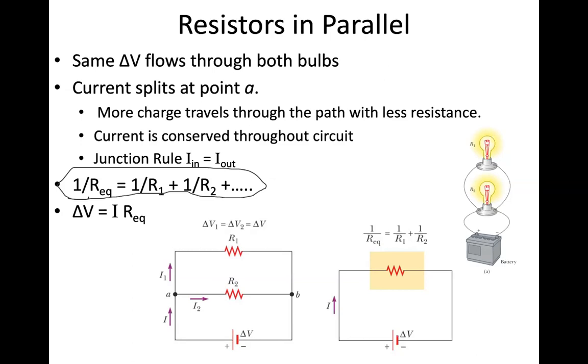So if I go to the store and there's only a 100 ohm resistor, but I need a 50 ohm resistor, well, I can take 100 with another 100 in parallel and create a 50 ohm resistor, reduce the resistance. Okay, so again, we want one equivalent resistance with our voltage in order to use Ohm's law. So we're still going to use Ohm's law.